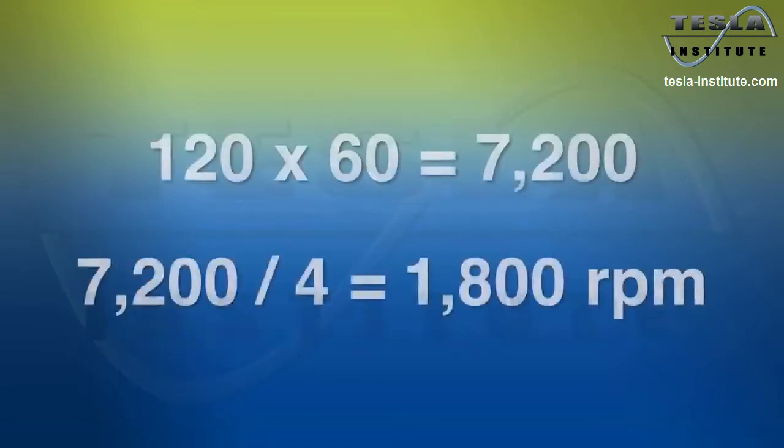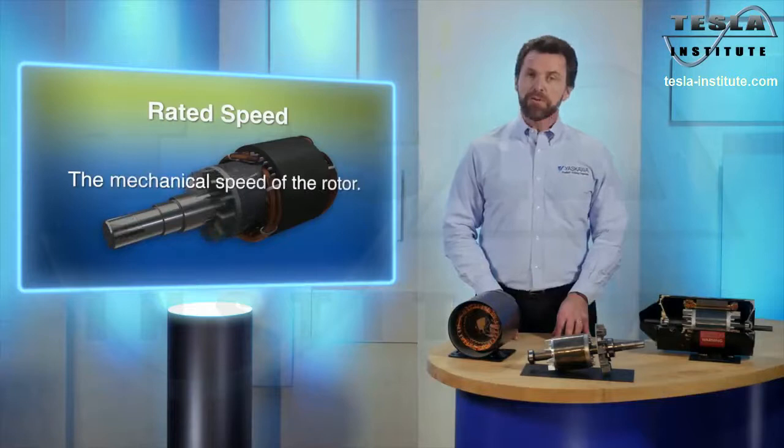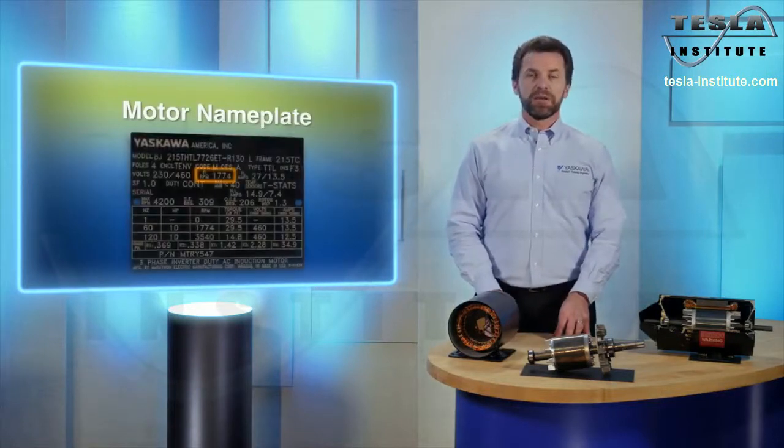So, with some simple math, you can see that a 4-pole motor connected to a 60 Hz power source would have a sync speed of 1800 RPM. The mechanical speed of the rotor is called the rated speed. A rated speed is based off a motor's rated load.